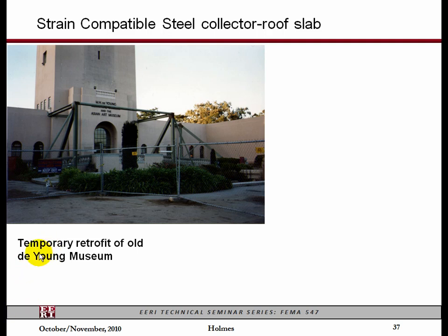But these exterior steel frames went across the top of the roof, and to pour concrete up there was very difficult, so that's where we devised this steel plate connector for collectors to get to these exterior steel braces. Again, it's the same old problem. Exterior solutions are wonderful, but you've got to figure out how you're going to get the load to these elements.